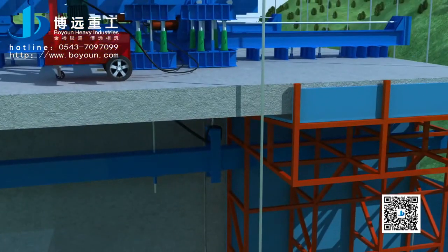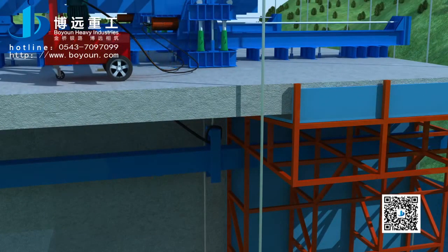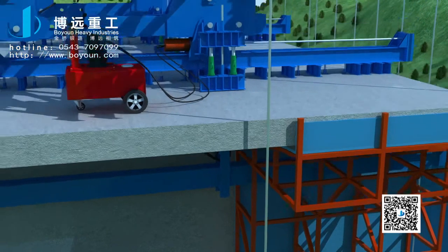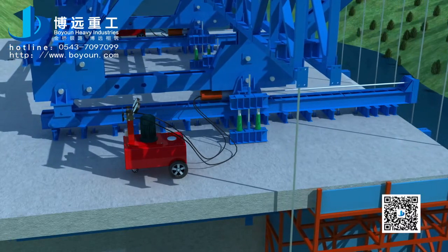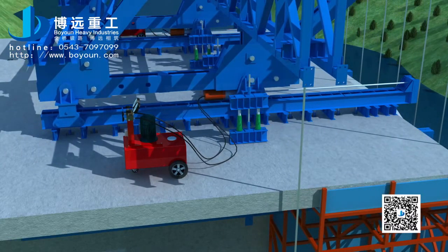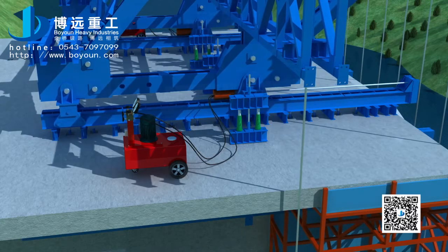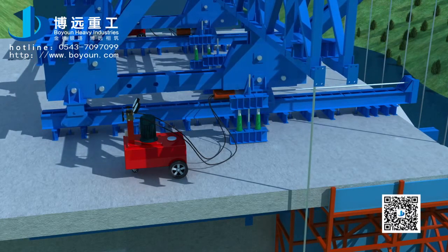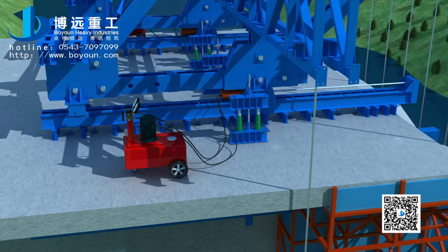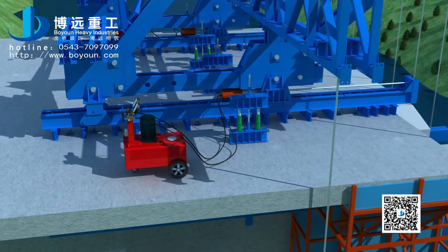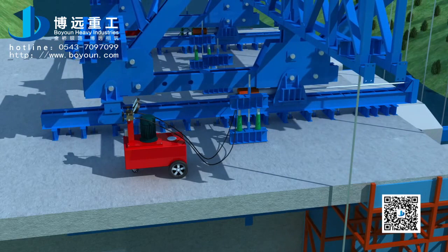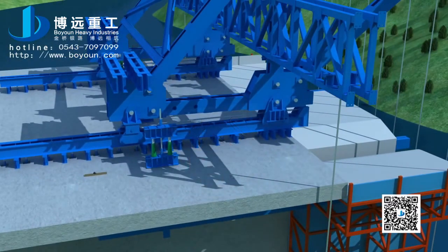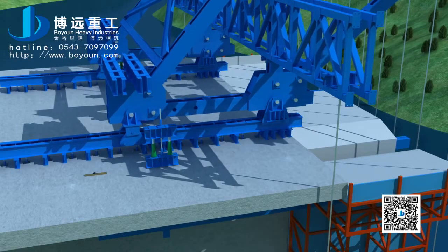Remove internal and external nose girder bearing plate. Make the stress of the nose girder transfer to the rolling hanger frame. Reverse bolt fixes the rolling hanger frame and use the oil pump to control the hydraulic jack to drive the hanging basket and formwork overall to slide forward at the same time. In the process of walking, must carry out real-time monitoring of the forming traveller in case of too much resistance or walking out of synchronization, etc., which should be treated in a timely manner. Until the forming traveller moves in place, improve the anchoring system in time.